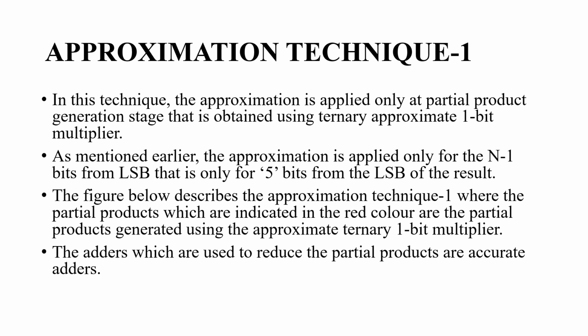In approximation technique 1, the approximation is only applied in the partial product generation stage. Only the ternary 1-bit multipliers are approximated. The ternary half adders or full adders which are used to reduce the partial products are not approximated.